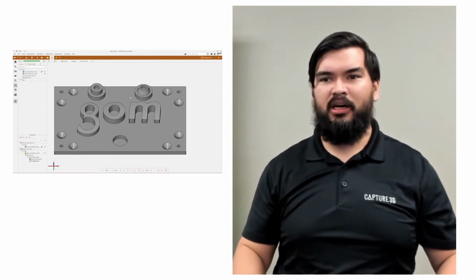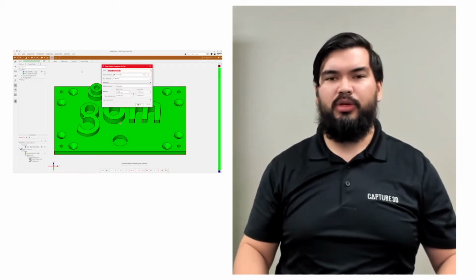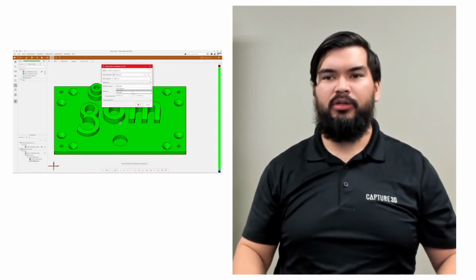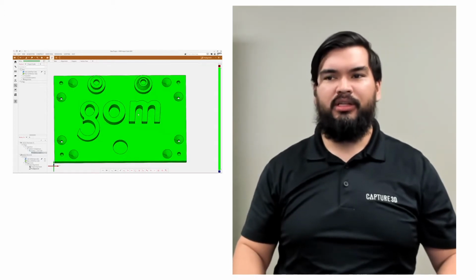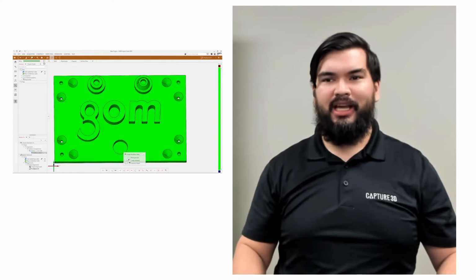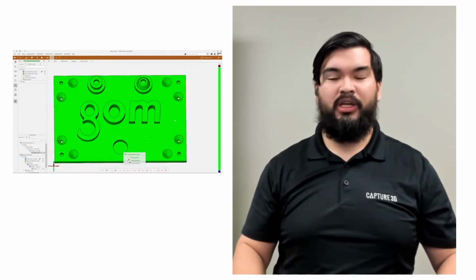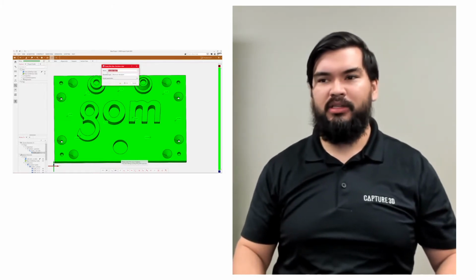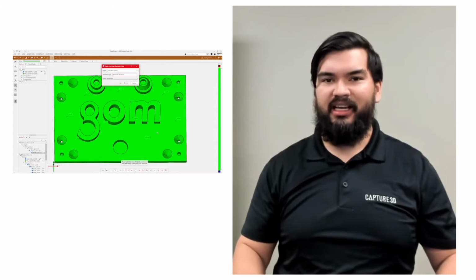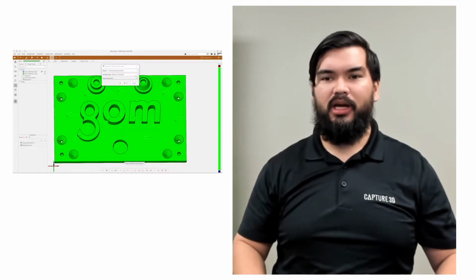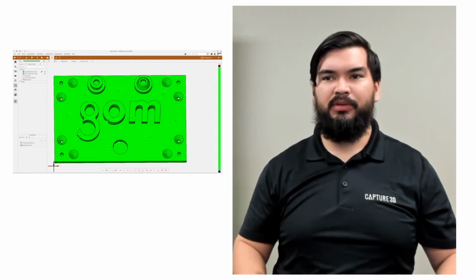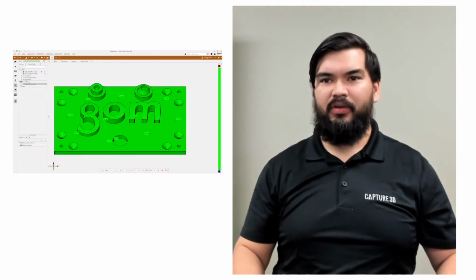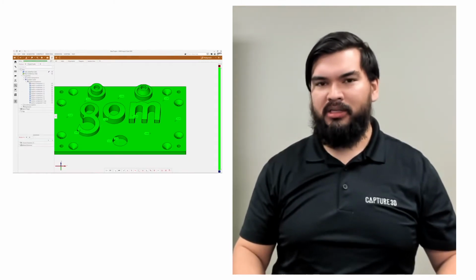A CAD inspection plan is a company-specific set of measurement criteria to achieve quality control using CAD as nominal, meaning we are going to use the perfect digital representation to compare your scan data to. So when taking advantage of this inspection plan, we can see some benefits. Generally, using a CAD inspection plan can streamline your inspection process by creating a robust process that can be repeatable. We can utilize a CAD inspection plan during multiple stages of a manufacturing process and at different milestones, like a PPAP, first article, and process capability studies.